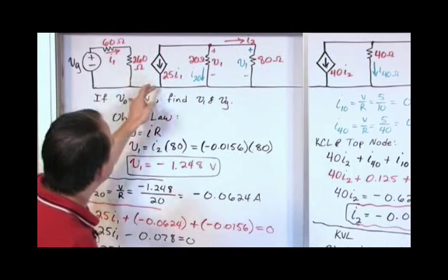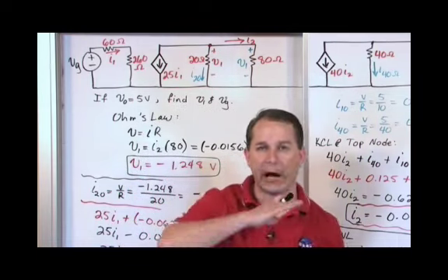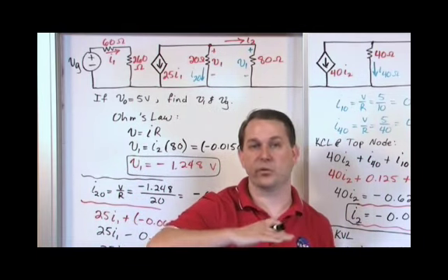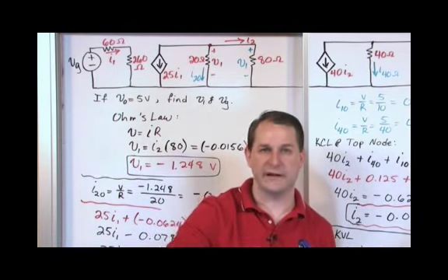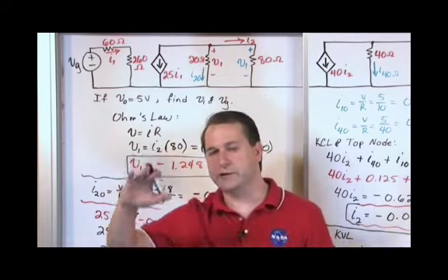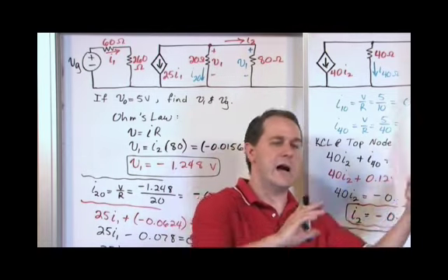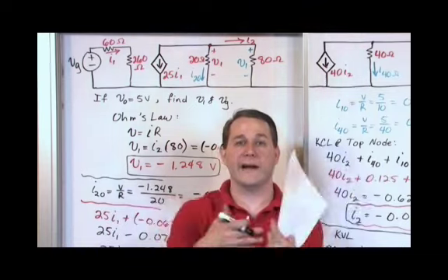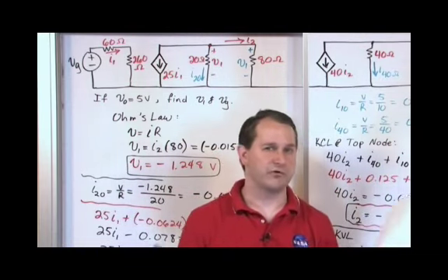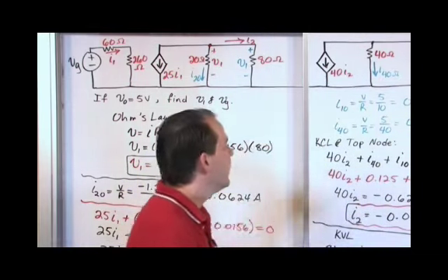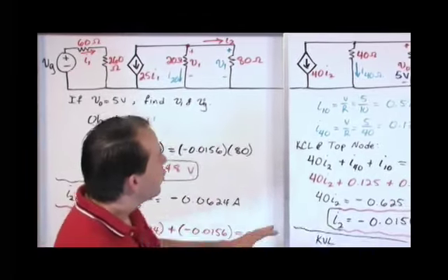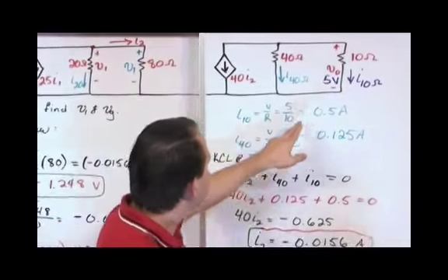Because don't forget, this is a current source, but there's a voltage across it, right? There's a voltage across this guy. All this is doing at the bottom is ensuring that the bottom of all of these voltages for these sources are the same physical potential. So you don't have any floating potentials, and anybody here that's operating higher and anybody here is operating lower, creating dangerous voltage drops between your circuit elements. So that's what this is really doing.